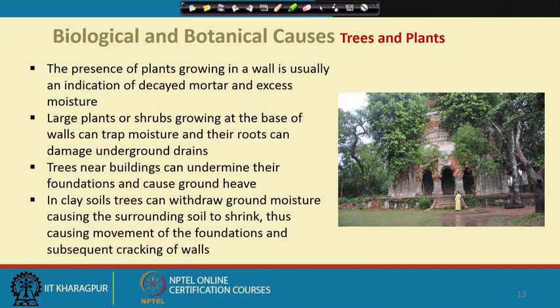It is very important. Again and again I am saying that when a small sapling comes, sometimes the drain gets blocked and dust particles accumulate, a bird brings a seed, and that seed becomes a sapling. It may be a banyan tree or some other huge tree, and this sapling starts growing. It not only penetrates the roots within the surface, but also blocks the flow of water. Sometimes it becomes so huge and the roots penetrate to such an extent that it becomes unmanageable, and then if we try to cut the roots, the entire structure collapses.